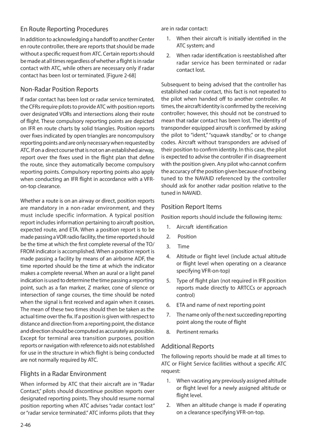En route reporting procedures. In addition to acknowledging a handoff to another center en route controller, there are reports that should be made without a specific request from ATC. Certain reports should be made at all times regardless of whether a flight is in radar contact with ATC, while others are necessary only if radar contact has been lost or terminated. Figure 268, non-radar position reports.